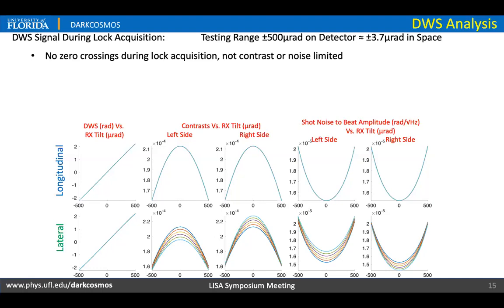By longitudinal, we're talking about the offset of the beam clip image in front of the photodiode, ranging from 0 to 1 centimeter. Lateral misalignments refers to a lateral shift of the RX beam, ranging from 0 to 100 micrometers.